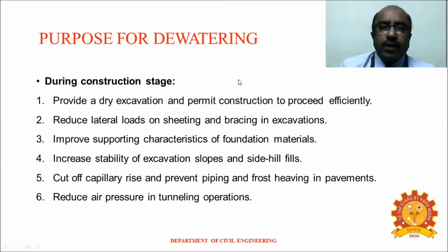What for are we going for this dewatering? During the construction stage, we won't have a dry excavation. Of course, from the ground level, if we have 1 meter or 1.5 meter or 2 meter, no problem. But whenever we want to go for deeper excavation, we may come across the groundwater table. So in that case, we need to dewater or bring down the groundwater table so that we can do the excavation in the right condition. So it will be safe.